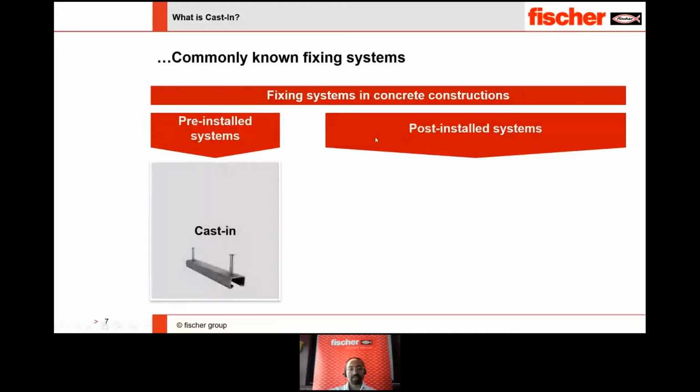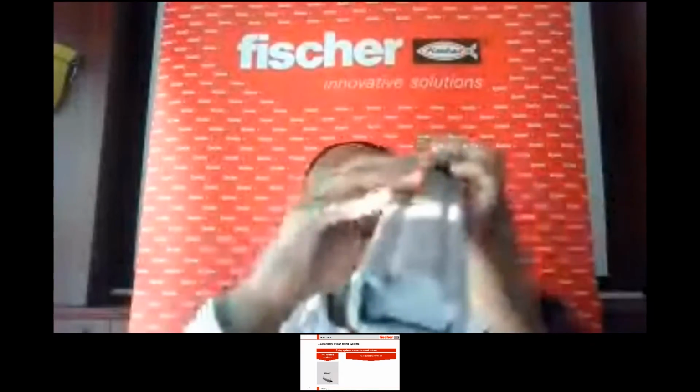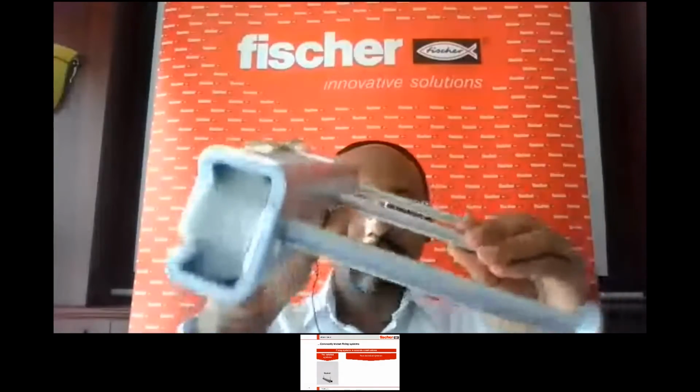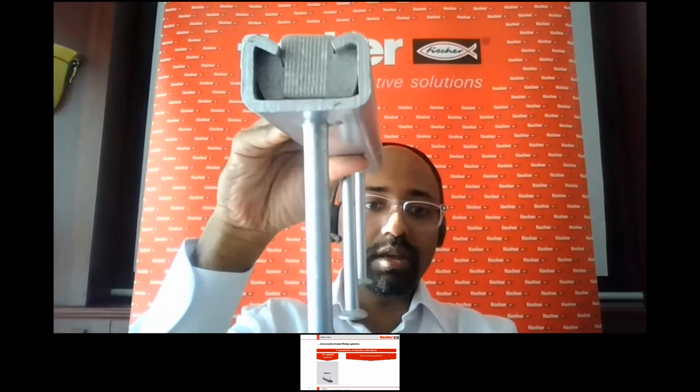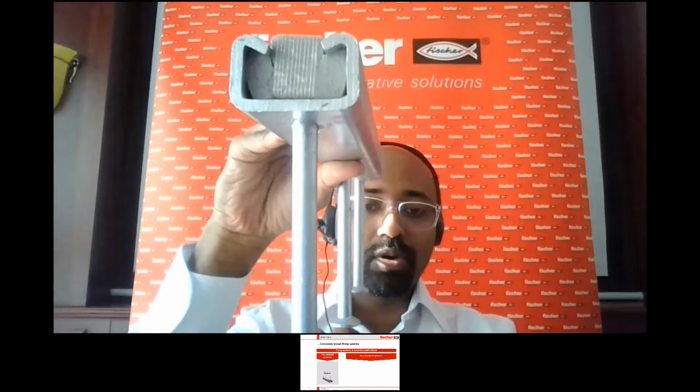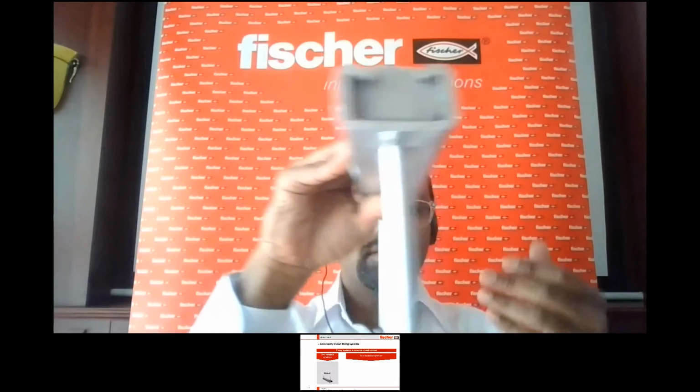So for pre-installed systems, an example is Fischer Cast-in channel. I would love to show a small sample of how it looks. I hope you can see my video. So you can see this is a sample of a Cast-in channel. This would be pre-installed inside concrete before you pour concrete, and then you pour over concrete and the concrete cures and this gets locked inside the concrete.